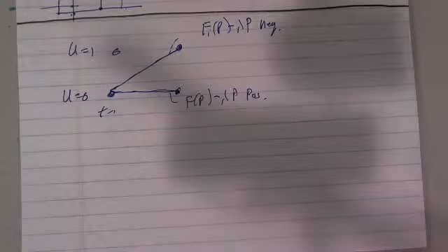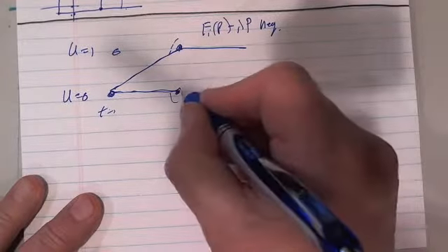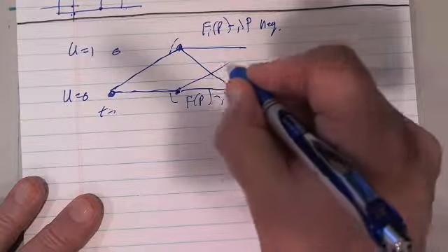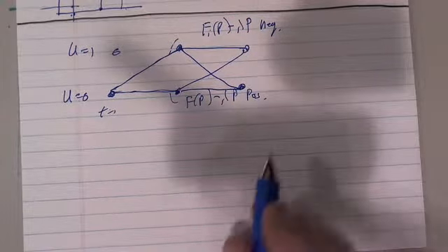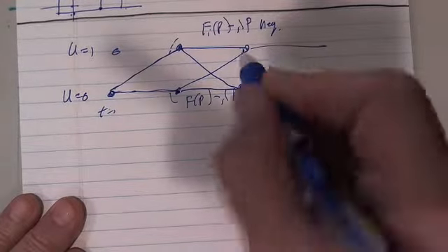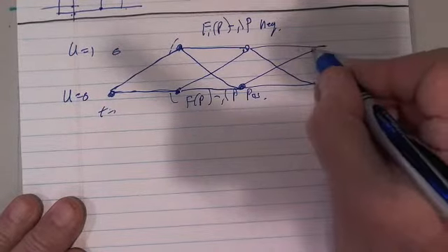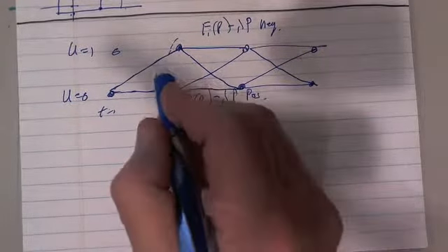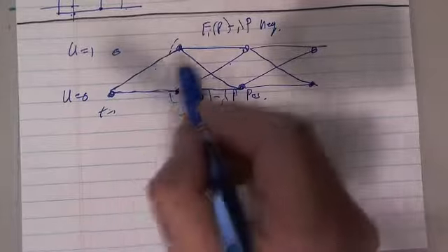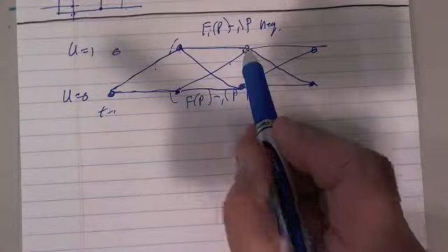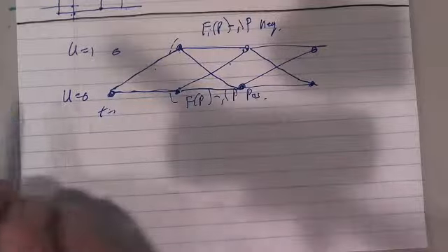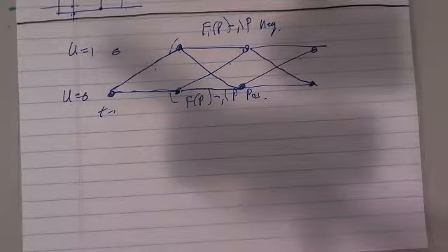So you actually now do a one generator dynamic program. It's one of the reasons you have to teach dynamic programming. Incidentally, if there were startups, we would have put them in the problem. If there were minimum up times, once you've turned it on, then this path is no longer valid. You can put all of those kinds of things in, but you have to do it for one generator at a time, and you get a set of solutions.